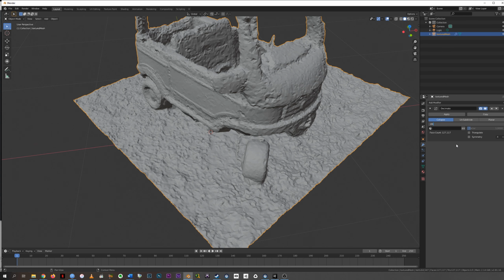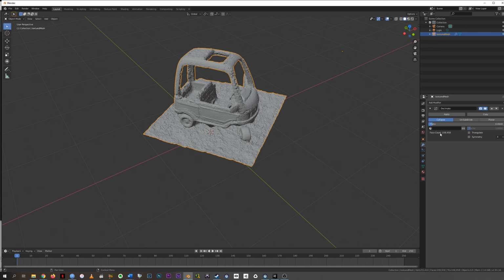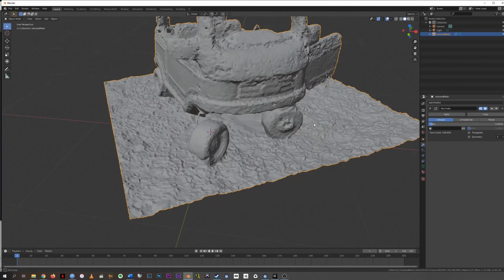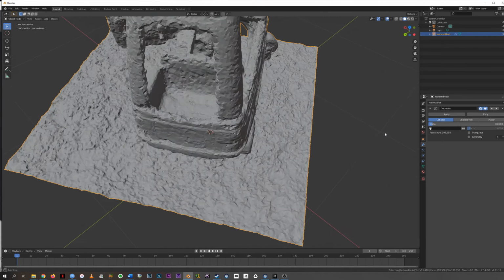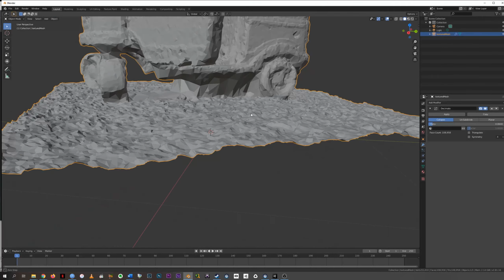So for this model, I think 0.06 is landing in a pretty good sweet spot, and that's very positive because we came down from nearly 2 million faces to only 100,000, and so then you could get more specific about your selection.